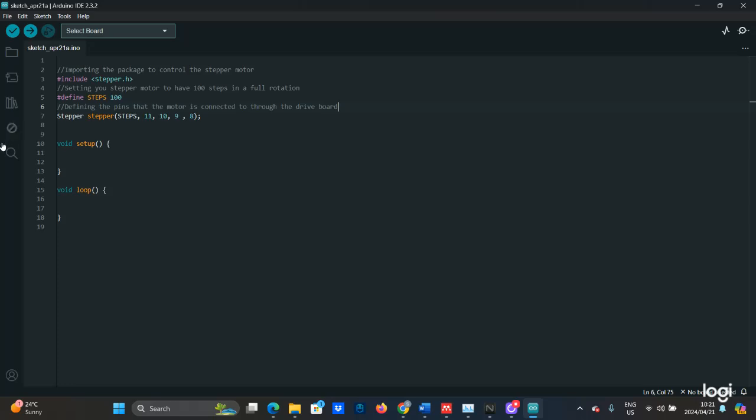So what you do next is you also have to define a variable that's going to store the previous readings. You will understand the importance of me creating this variable soon. This variable is going to store the readings of the previous speed of the stepper motor. You want to equate it to 0 because our stepper motor starts at 0, right?